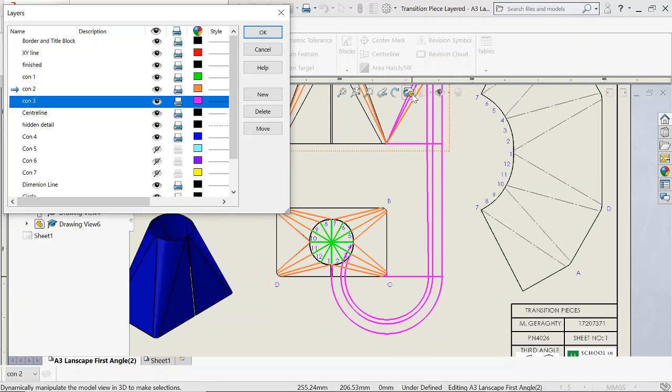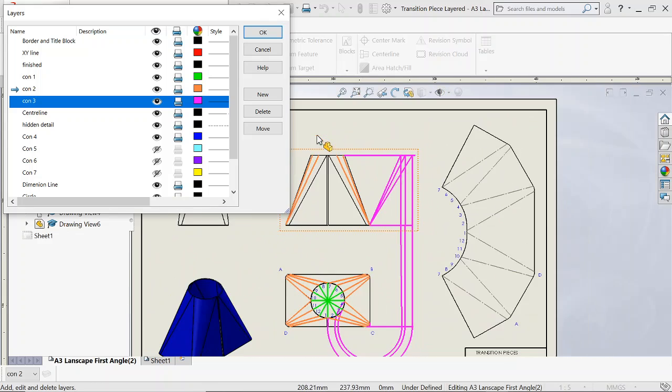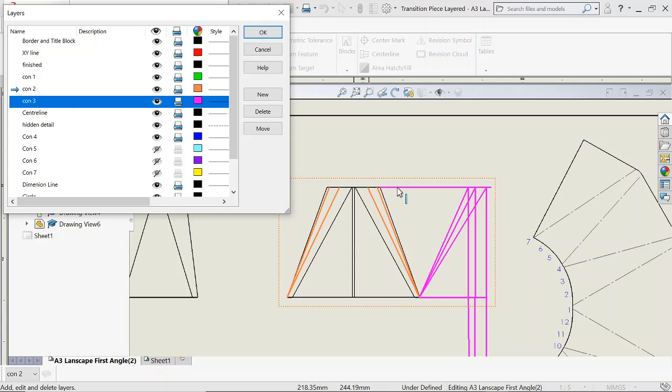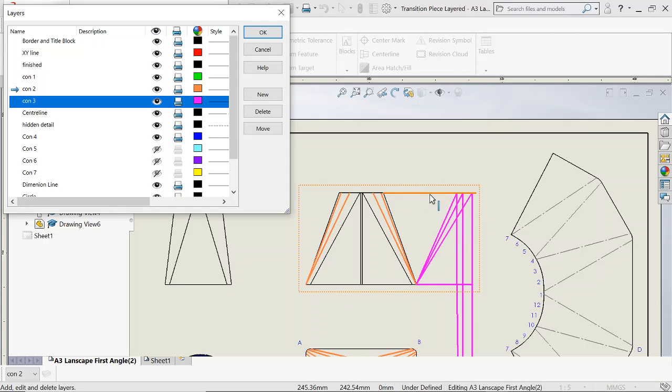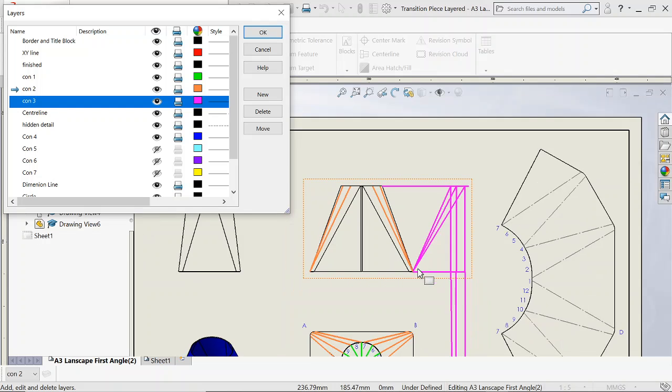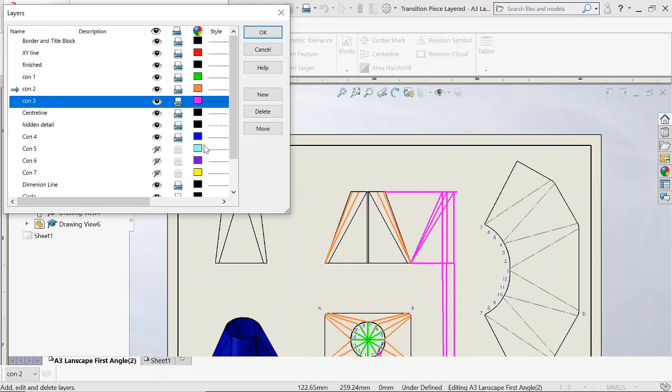We're bringing them vertically up until they hit this horizontal line, which is our height line that we brought out from elevation. So where these lines hit the horizontal line, from our corner, we bring them out to where they hit the vertical line and back into our corner. So let's see if our three lines from the vertical lines up are brought back into our corner. Now these lines are our true length lines.